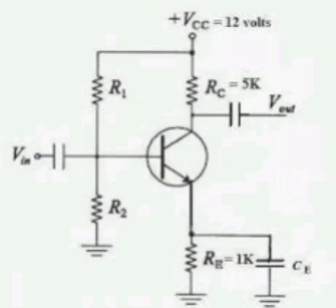In an induction machine, the relative motion between the stator rotating magnetic field and the rotor induces current in the rotor, leading to the development of torque and mechanical energy. Slip, the difference between the synchronous speed of the magnetic field and the actual speed of the rotor, adds to their complexity compared to transformers.